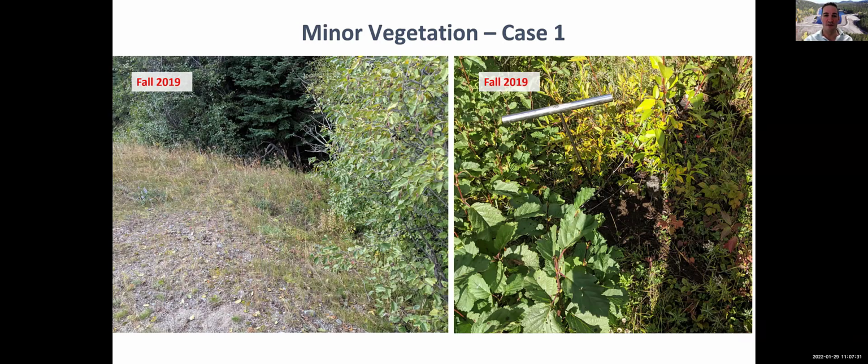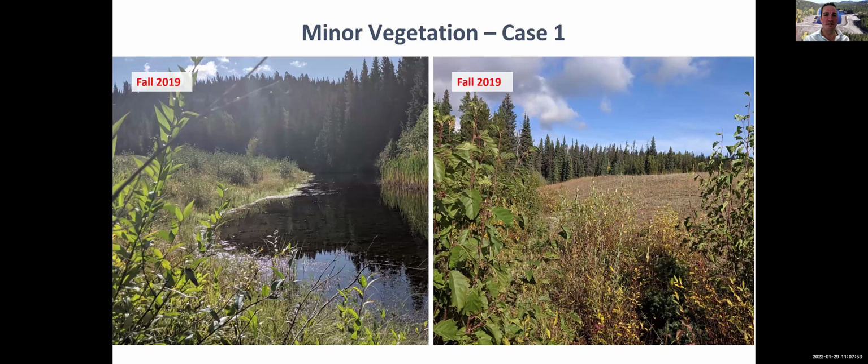You don't really have a clear interface area. Same area, walking around, you see that's actually a photo of quite a bit of diggings, right? Or like cutting a burrow, right? Where they dig down and pull the material out of the embankment. So lots of little things like that were found in this particular case, excessive seepage, a number of things.